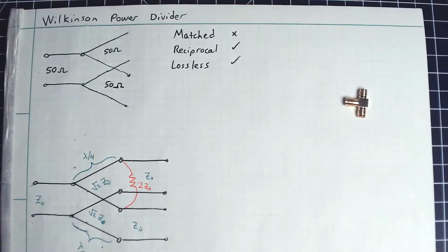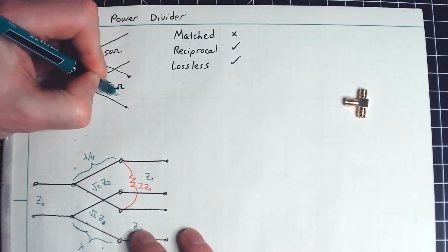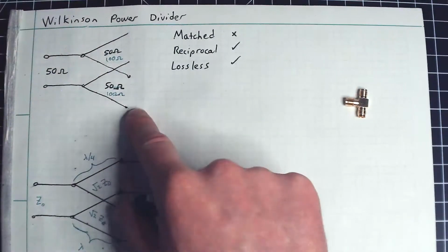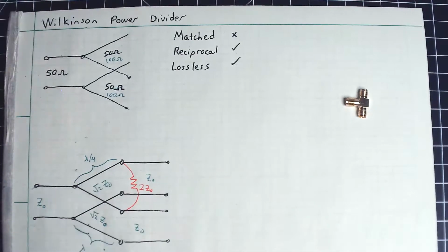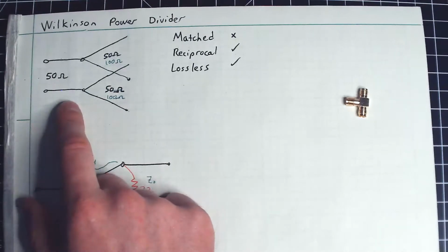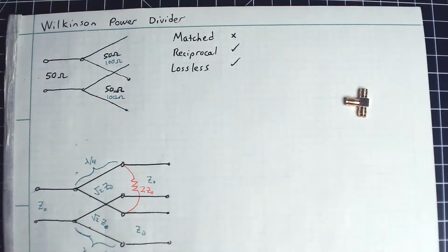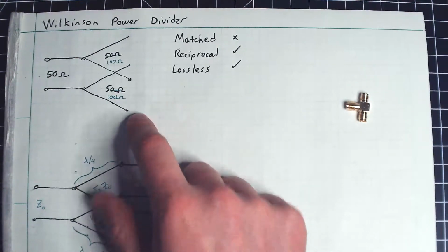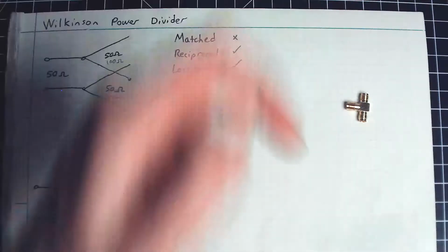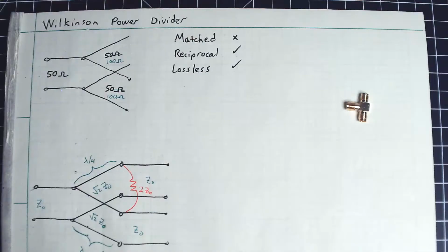And it's tempting to try and cheat this a little bit. For example, suppose instead of 50 ohms, I replace this with 100 ohms, like this. So I have a 50 ohm line feeding a split into two 100 ohm segments. And now you can see how the equivalent input impedance, seen looking down here, will in fact be a match at this port. And so maybe that's great, but that's not entirely desirable because now I have to deal with a 100 ohm line instead of the usual 50 ohms. So either everything else down here has to be designed with 100 ohm impedance in mind, or I have to insert some kind of impedance transformer to bring everything back down to 50 ohms in order to make this work.